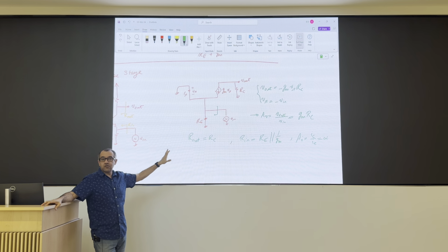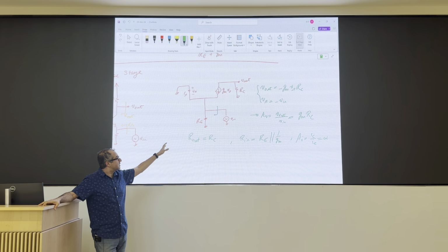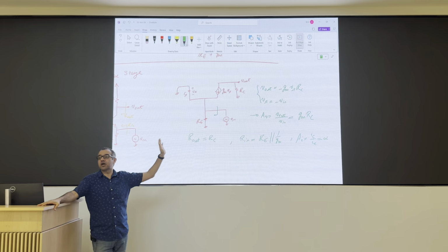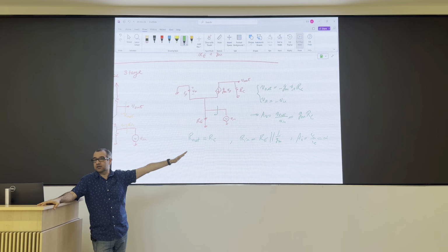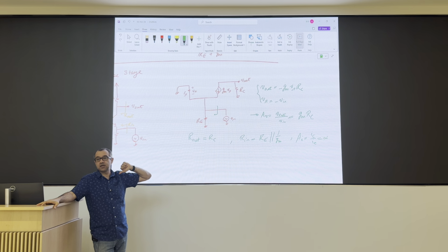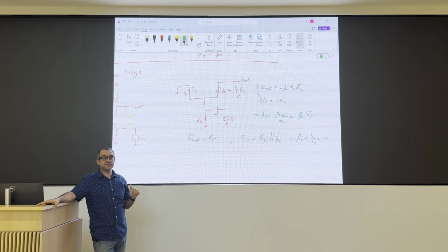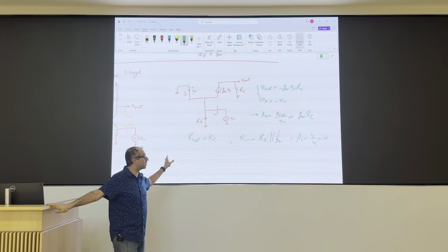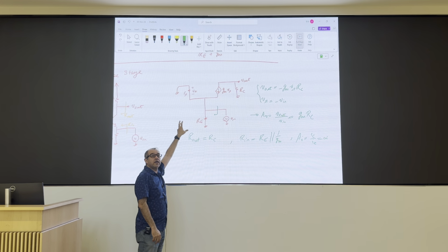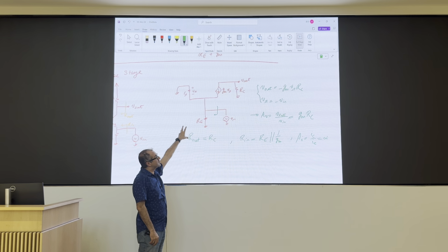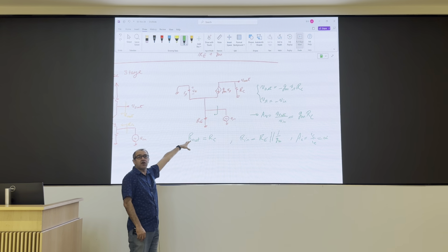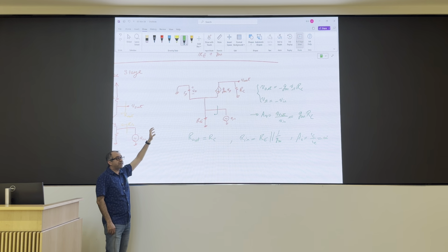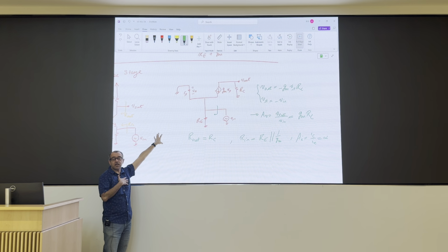For the same resistor, same gain, similar components, this has a much higher bandwidth compared to the common emitter stage. So when you look at RF circuits, you see more common base than common emitter. For RF applications, it has another advantage that we like.